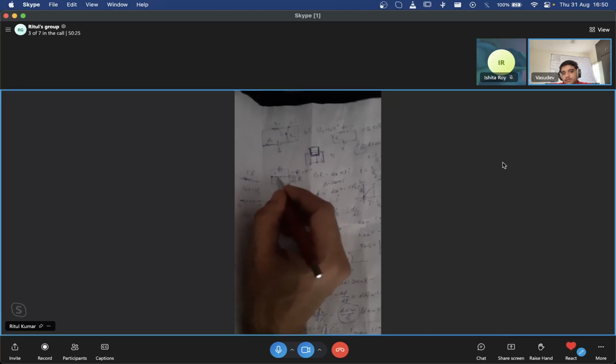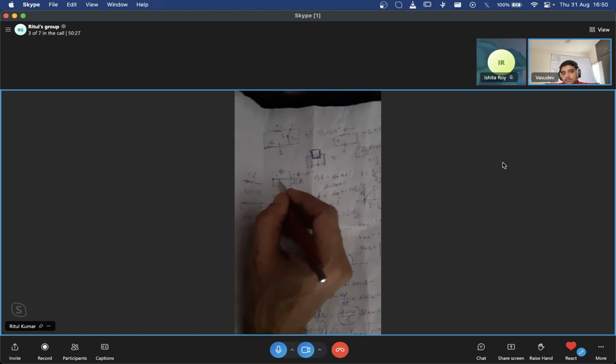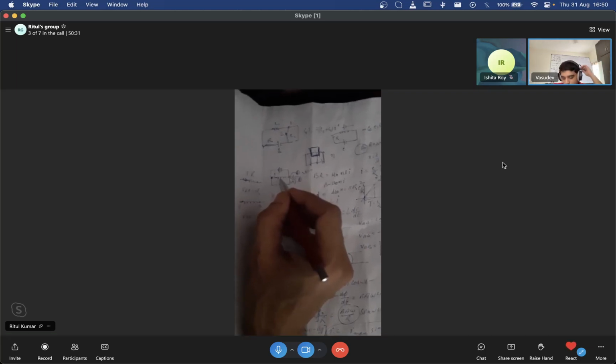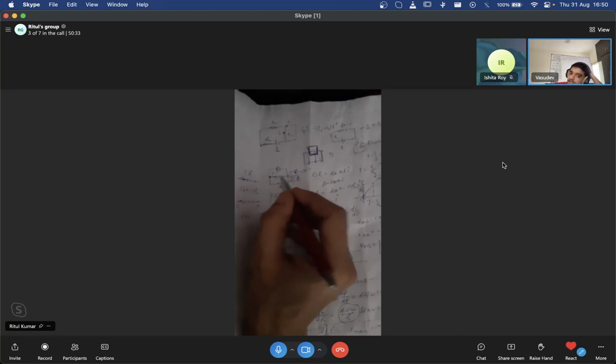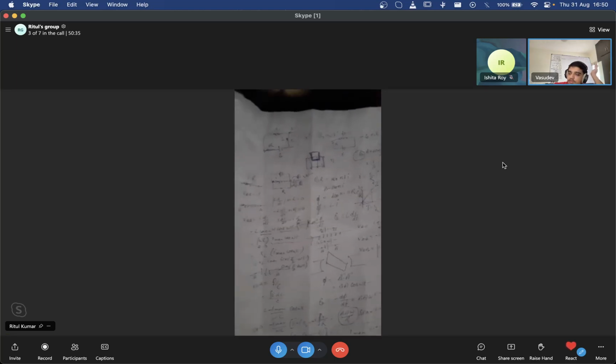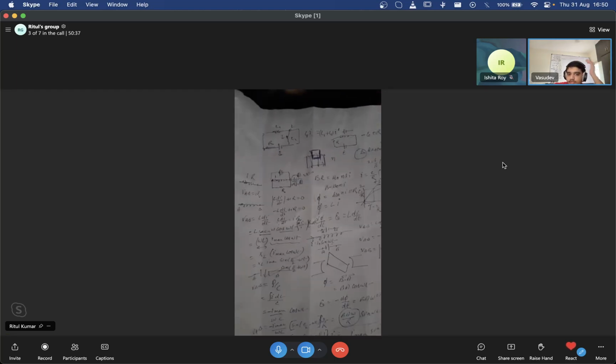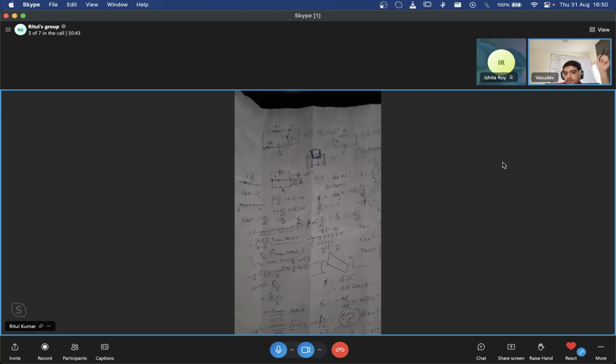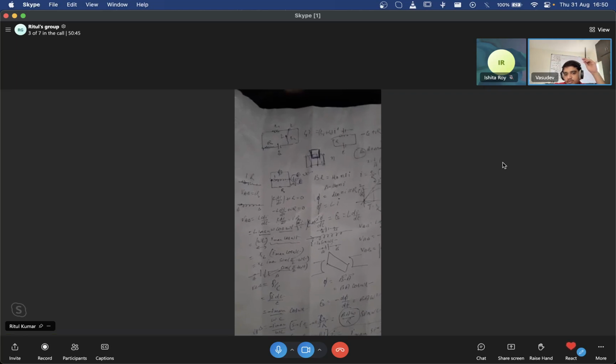How do you know this is high? That is the entire question, which end will be high, which end low. How is it known to you? So I'm saying if we assume the first one's right and we go clockwise, we know the current has to be, at least initially, clockwise, right? Because that was how it was set up by the battery. Correct. So the potential must drop across the resistor. It's also dropping across the battery, and that's not possible. I mean, that lost potential has to be made up, or Kirchhoff's voltage law is violated.